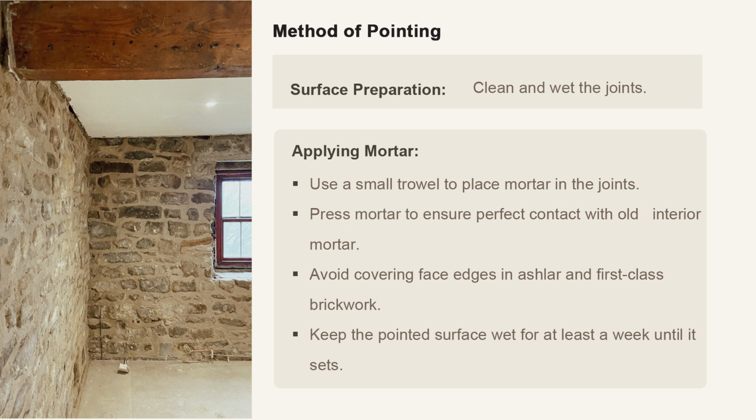If we use lime mortar, you mix 1 part of lime with 2 parts of sand or surki. This is made by grinding fat lime in a mortar mill. If you use cement mortar for pointing, the mix ratio you have to choose is 1 part of cement to 3 parts of sand. So, what would be the steps in preparing this for masonry?